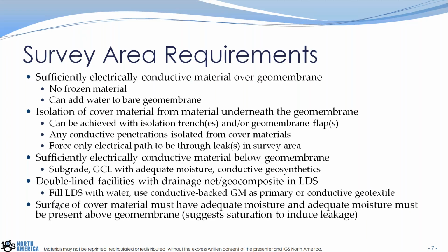We have a question in the question box. Why is it called arc testing, not spark testing? So spark testing is specifically for conductive-backed geomembrane products. Arc testing refers to when you're testing any geomembrane and you're grounded to the underlying conductive material. Just that one question. So that's the difference.